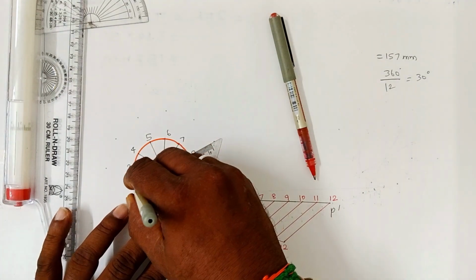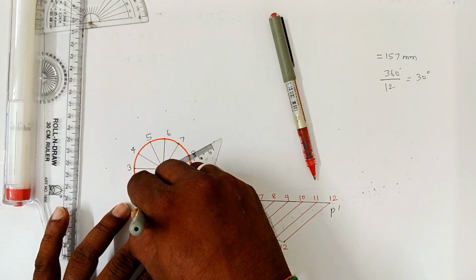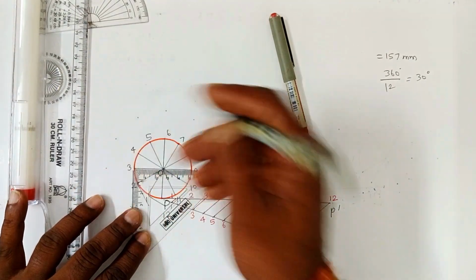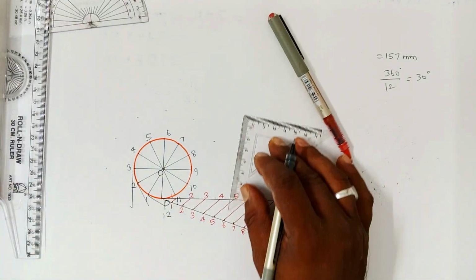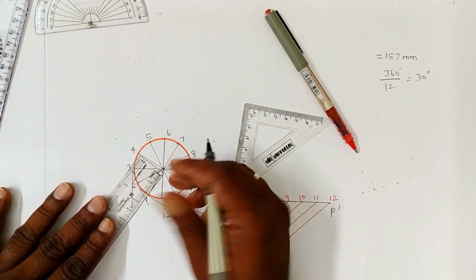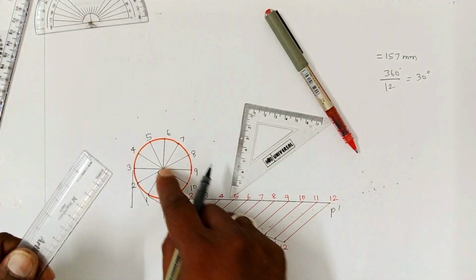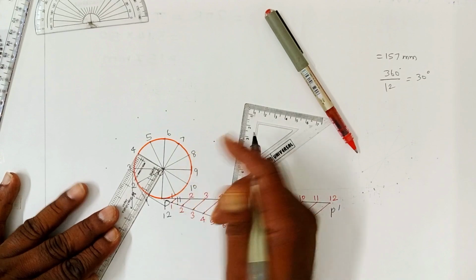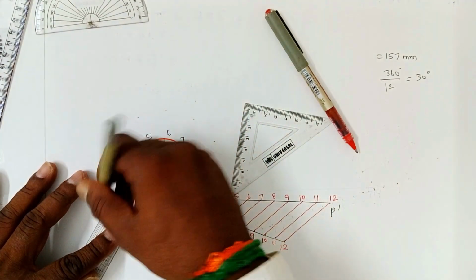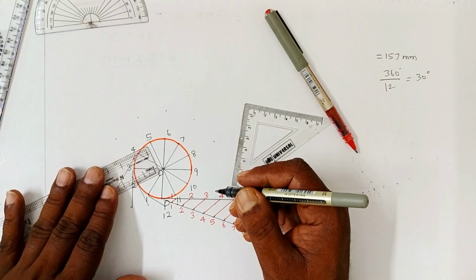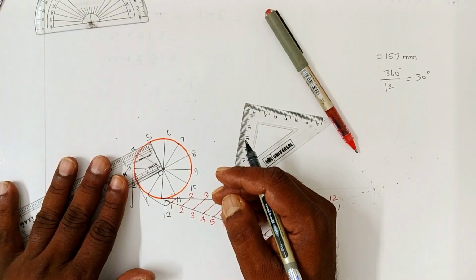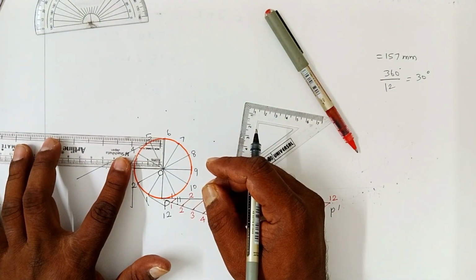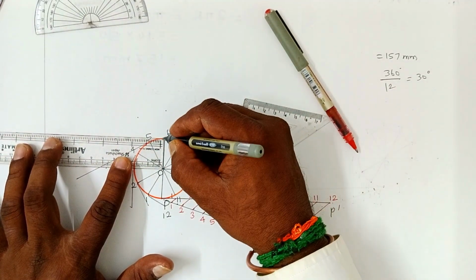Okay, draw a line like this using the other edge. Similarly, O3. These are 90 degree perpendicular lines we are drawing. Or if you don't have a set square, you can draw it using a scale also. Keep the short edge of your scale in coincidence with the radial line, at point 4 as the corner of your scale. Okay, like this, and draw using the longer edge of your scale. Similarly, O5. Draw lines like this, called tangential lines to the radial lines drawn.